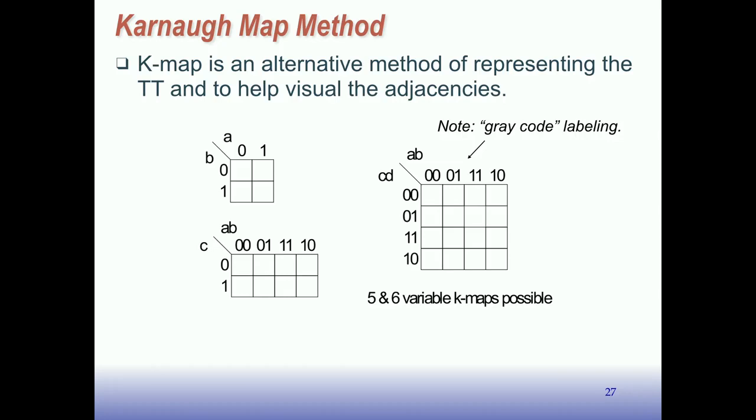This is not a standard binary. If you think about counting in binary, we go all zeros, and then we have a 1, and then the ones are moving in a little at a time. Eventually, we get to all ones. The next step, we go to almost all zeros, except for a 1 in the high position. There we're changing lots of bits at once. Okay. We can talk later about the usefulness of gray codes, but this is one place to use gray codes because it helps make this easier, and it makes the whole technique work.